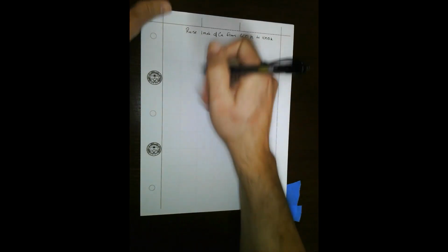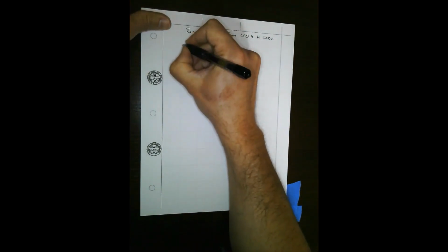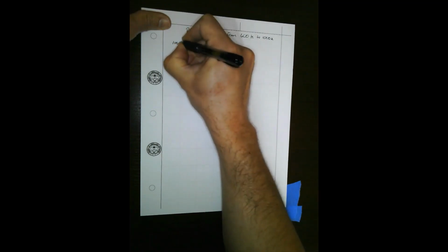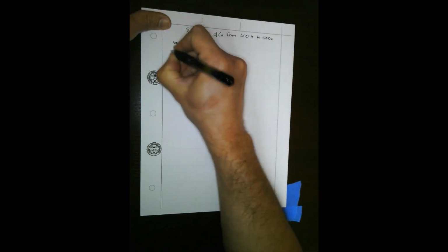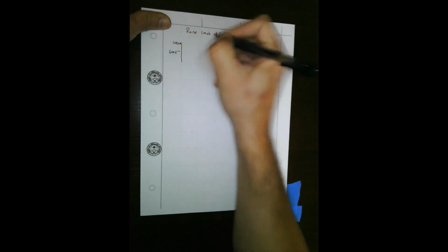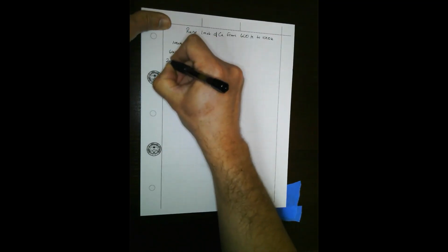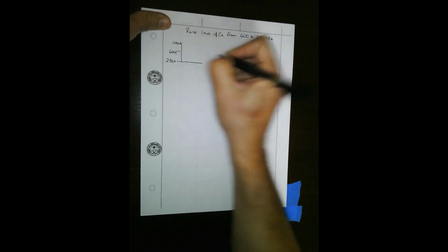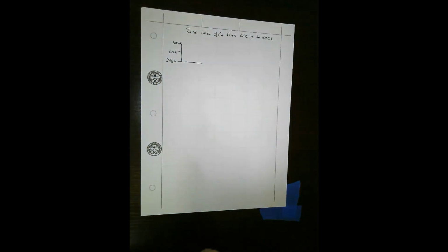And so what's the trick when we're using the tables and sensible heat? You always want to think of it in terms of giving respect to room temperature. We want to get to 1,000 K. We're at 600 K, and everything's with respect to 298 K. It helps to get in the habit of diagramming your processes because it keeps things clear.